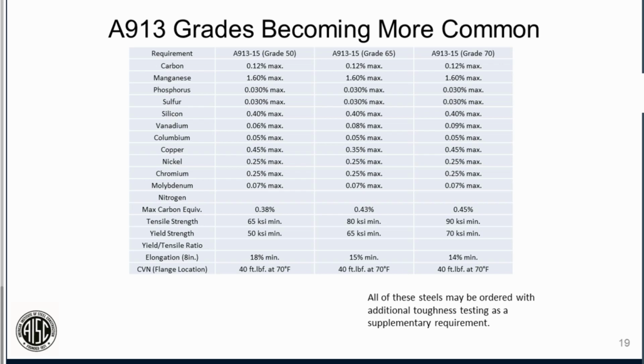So pretty exciting stuff. And this one's unique. It actually has a Charpy V-notch. It's specified by the spec, the very last line, and that's unique. You don't see that everywhere. That is unique to that grade. So basically, you're mandating a certain level of toughness in the steel. So that's an innovative aspect of that grade. So we move to the next slide, please.